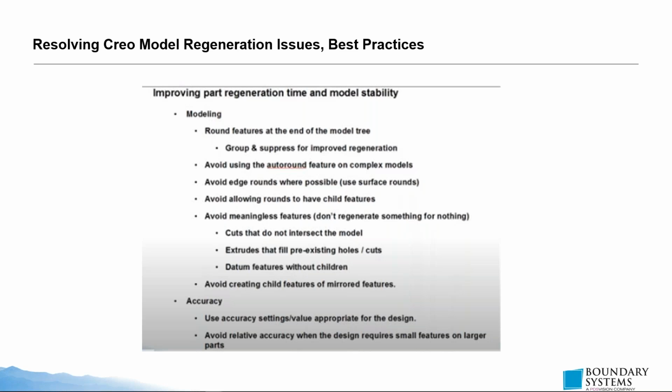I do think it is useful for things like castings that have standard rounds: everything is this value, unless otherwise specified. If you're using that function for a casting, then first create all of your "otherwise specified" rounds. Anything that is not of the standard size, you would create first and then use the auto round function.